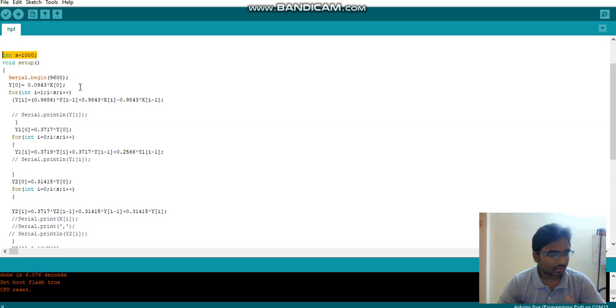When we convert this into the time domain, we will get y of n plus 1 minus 0.9686 into y of n equals 0.9843 into x of n plus 1 minus 0.9843 into x of n. When we convert this into a causal system, we should not have any n plus terms. We should contain only the n term and n minus 1 term. So replace n plus 1 by n. Then we will get y of n equals 0.9686 into y of n minus 1 plus 0.9843 into x of n minus 0.9843 into x of n minus 1.